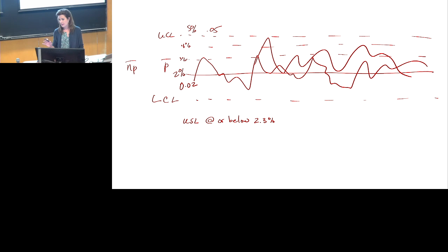Now, the other part of this is calculating a CPK equivalent, right? And of course, when we're looking at a regular CPK, we're looking at whatever's the closest spec limit to the mean and dividing that by 3 sigma. So we're looking at half curve widths. But what this really relates to is your percent out of spec related to that closest spec limit, what you expect to see for your percent out of specification, either on the high side or the low side or both.